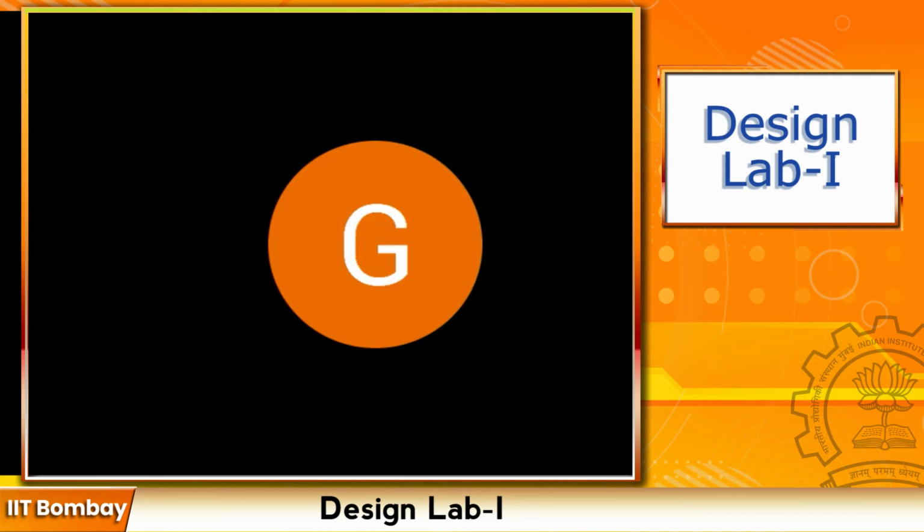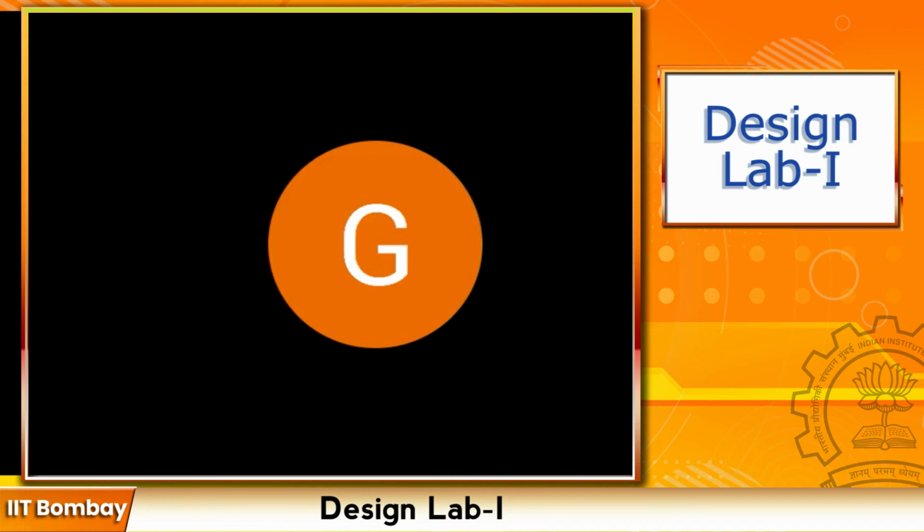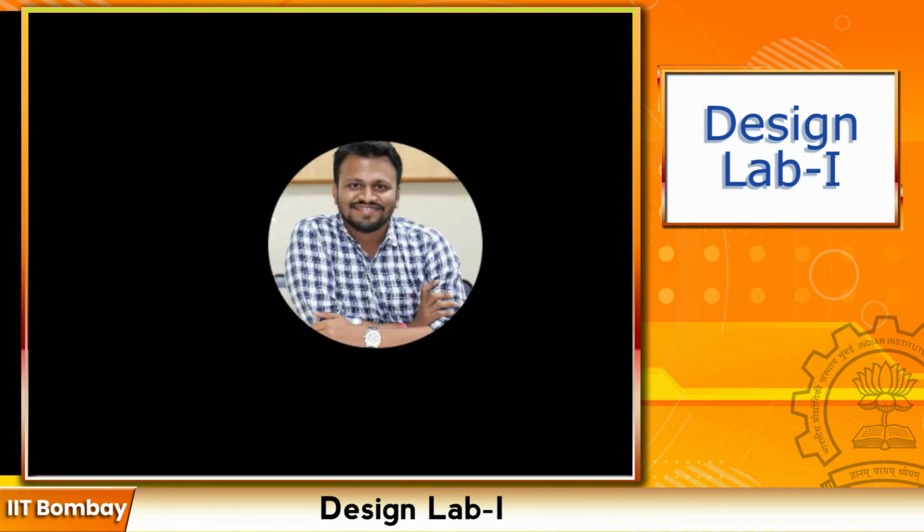Hello, Priyam. Yes, I corrected everything, the brackets for question number 5, numerator and denominator of the rate law. But now the error that is popping up is nested loops. The flash algorithm was unable to converge to a solution. The mitigation actions are to try another property package and/or flash algorithms. I'm not able to figure out what went wrong. I have rechecked the numerator and denominator.